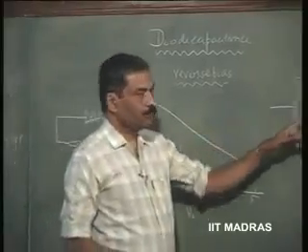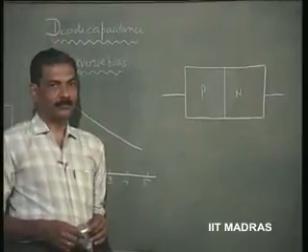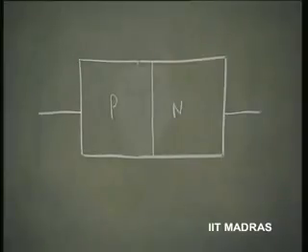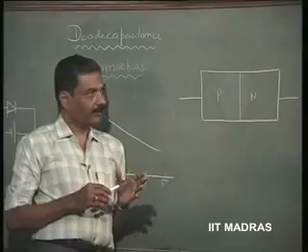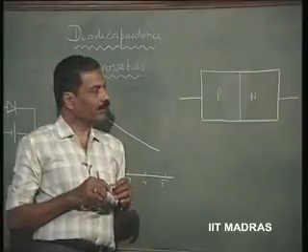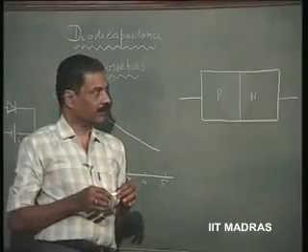Consider the PN junction. This is the semiconductor diode. I have told you earlier, by formulating a PN junction like this, we are able to get the IV characteristics that are pretty close to the ideal diode. The IV characteristic being the exponentially related characteristic between current and voltage. Now, apart from that, we would like to see what other terminal characteristics the diode represents.